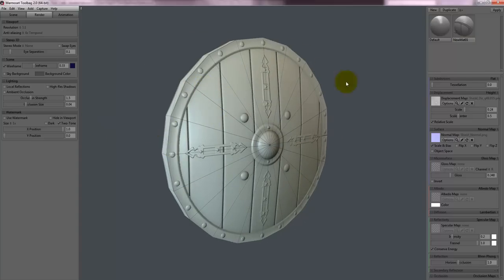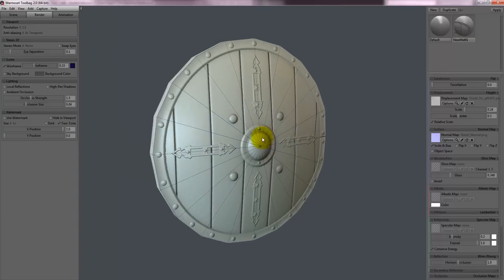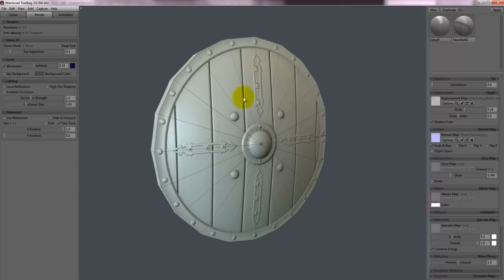UVW for both of our low poly meshes, for the newer one and this one, are the same. So we can put the bake, or the height map, on this one, and because our UVW coordinates are the same, they will still work. We only created the other version of the low poly, or the newer version, so that we could get the bake to come out right.